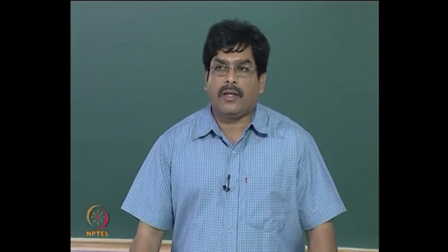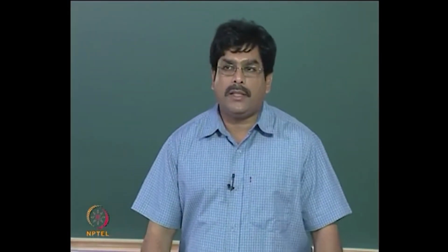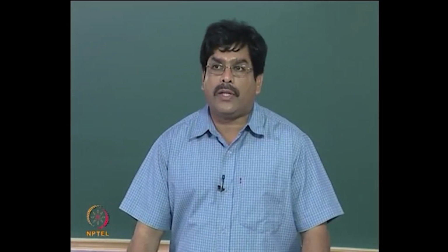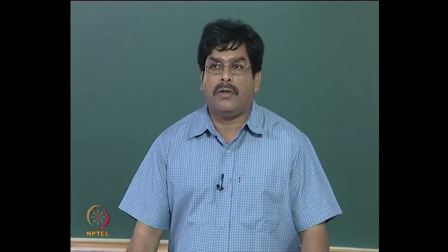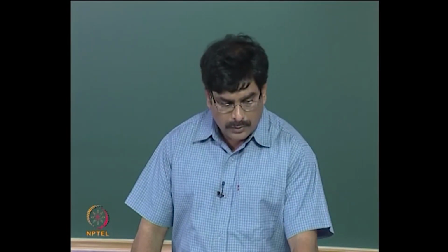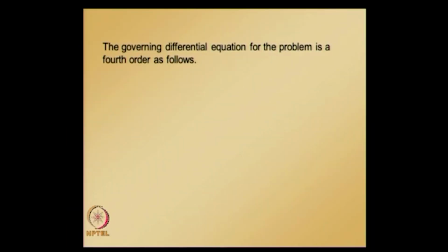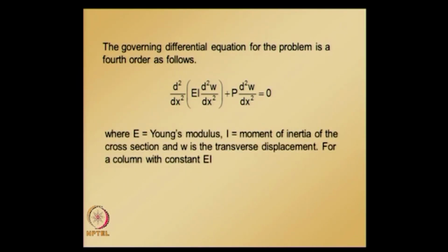Before we proceed, we will briefly review the boundary conditions and how the governing differential equation corresponding to this problem can be brought into the form of a general one dimensional boundary value problem for which we developed the element equations. The governing differential equation for this simply supported column buckling problem is a 4th order differential equation subjected to the boundary conditions,